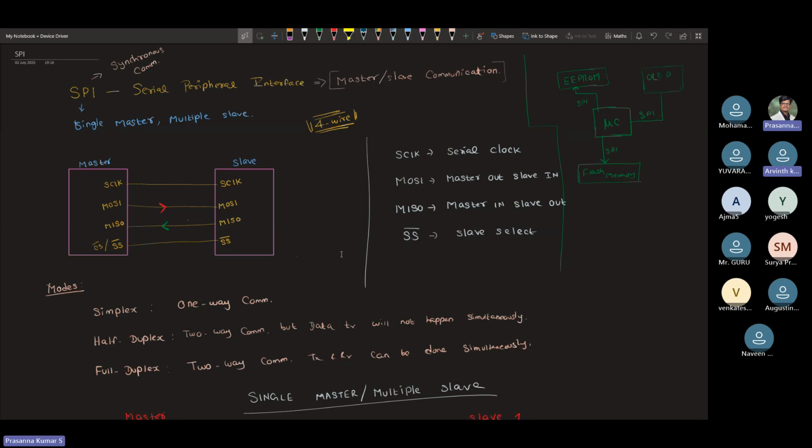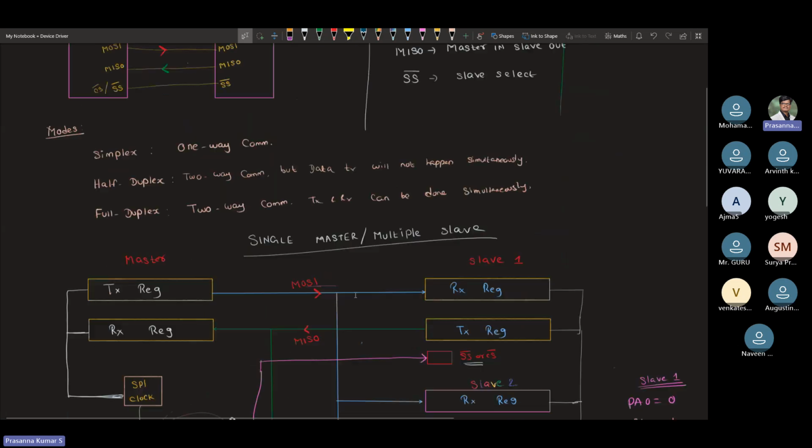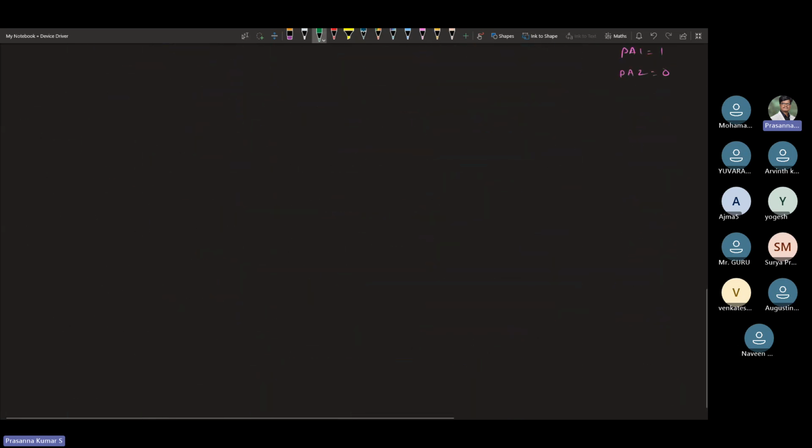We will get some values, I guess? No, the ultrasonic sensor is just going to transfer some pulses. We will count the number of pulses for a particular time period, and then calculate the distance. It won't transfer any values, only the pulses will be there. Got it.